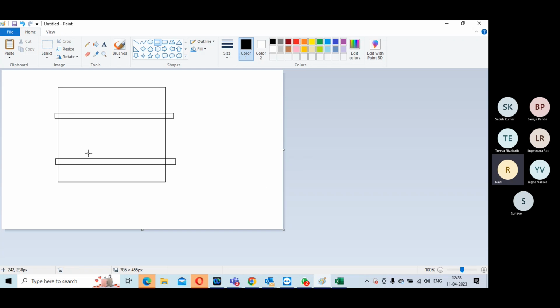Then this mesh is your always on power mesh, because this is connecting to M12. This M12 is connecting to your bump. Whatever is connecting to your bump is your always on, which you are not actually supposed to touch. Now you will have to create a separate strap mesh, but you are not supposed to connect this one. You are not supposed to add wires to this M12. This connection is your shut off domain.